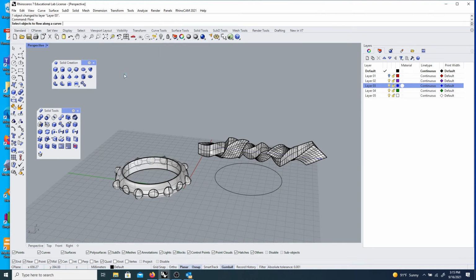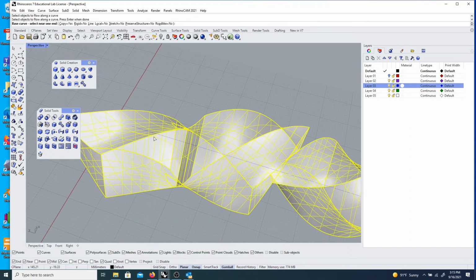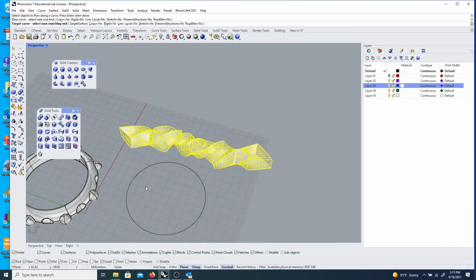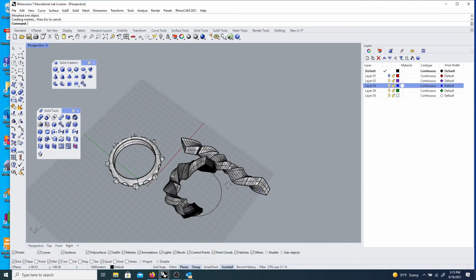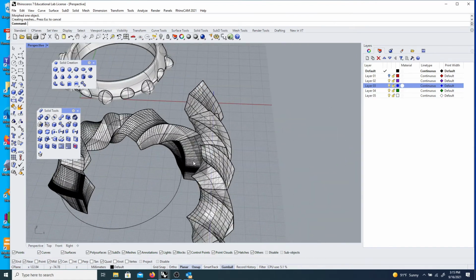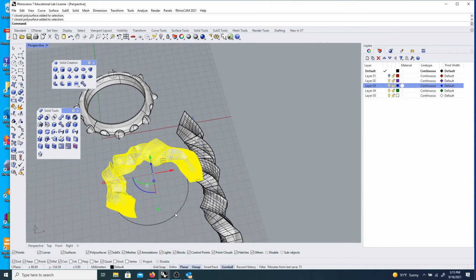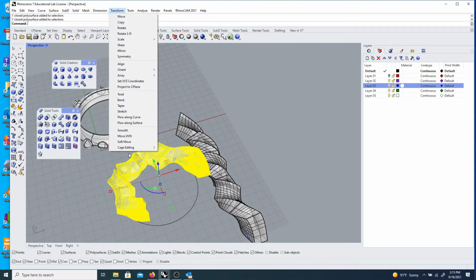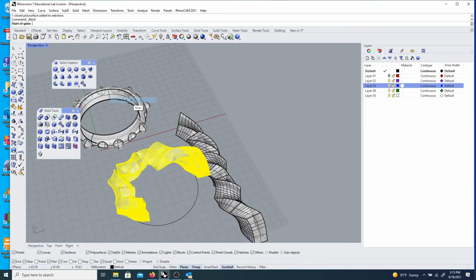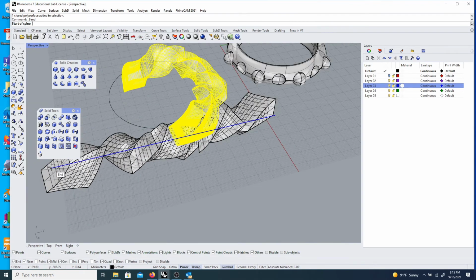So flow, base curve, target curve. What you gonna do? That's a little bit more interesting. So if it's a little bit out of whack, you can rebend your shape with the bend command. That's under transform, bend. And sometimes that's the way to bend things around.